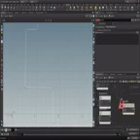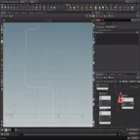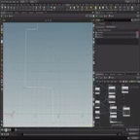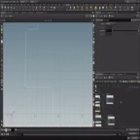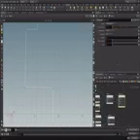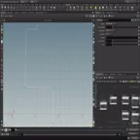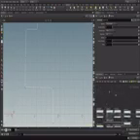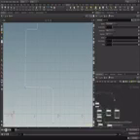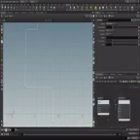This switch node needs this value to determine which values are going to be used. And let's wire those two in. There we go. And then a set attribute. We're going to set the position of the points because we're going to change their position. And for those of you who don't know that yet, if you press Alt, you can get these little bubbles, which help you to make a nice and clean system.